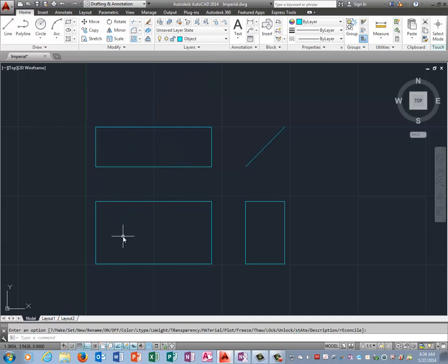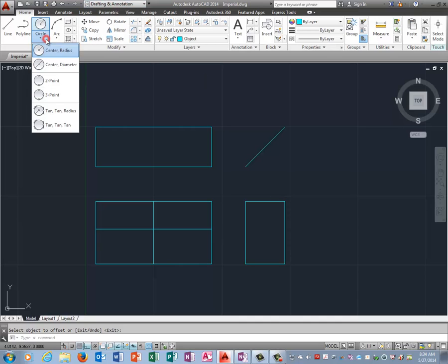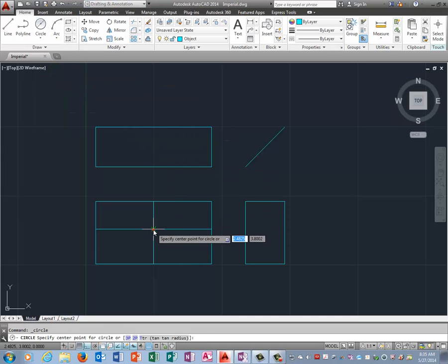So I'm going to start in the front view, and I'm going to start with the circle because that's the big commanding feature there, and I'm going to offset 2.12, and then it is 1.26 up from the bottom. Okay, and the diameter of this thing, circle center diameter, it gives me two different dimensions, but I'm going to use the common dimension, which is 1 1/8, which is 1.125.